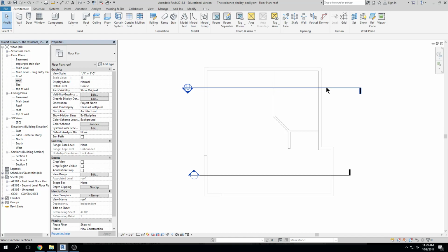We're going to go into sketch mode. You're going to use your existing building geometry to help you create your roof. You may have to create more than one roof, let me say that, which we'll talk about when we have to join and cut roofs. So we'll talk about that.